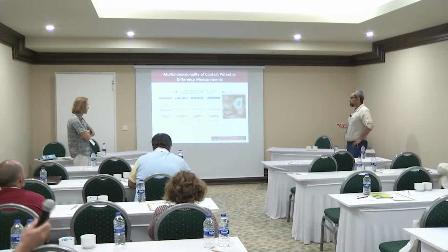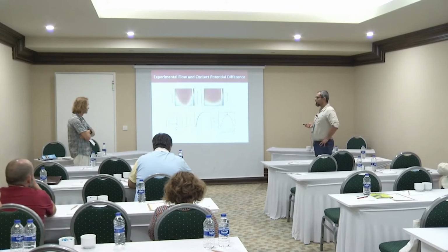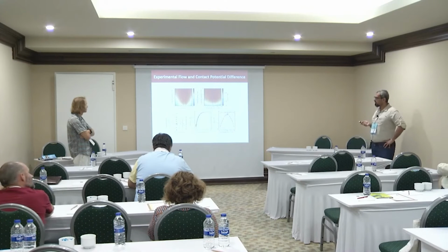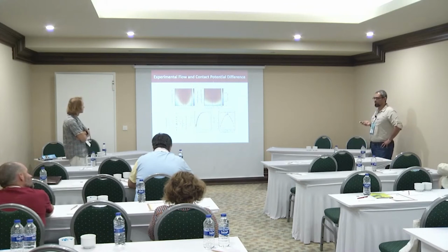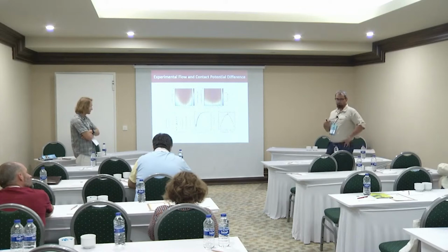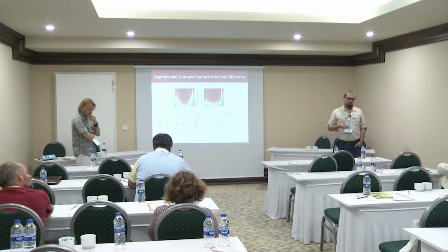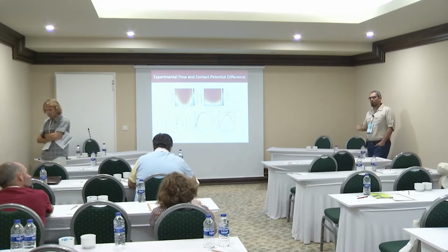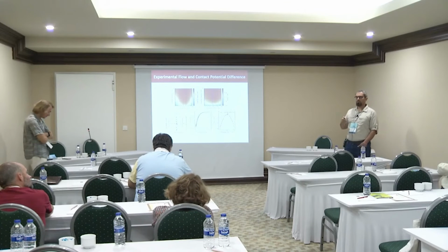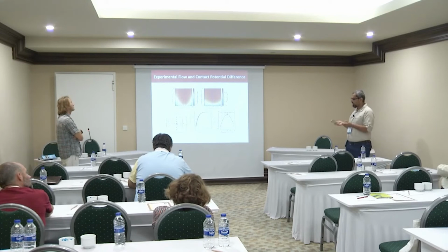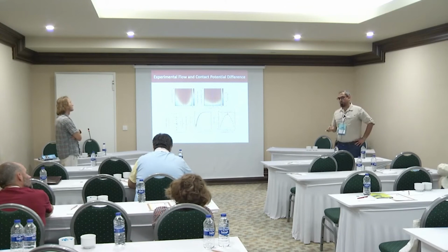Yes, we measured by using different types of cantilevers, and the most important part is that we are measuring the contact potential difference, not the actual Fermi level. So any chemical change in the tip, which may be induced under ambient conditions, may affect the absolute value of our measurement. So we did cyclic measurements. So we measured the properties at different temperatures, and we went back to the original temperature that we measured. Also, we used different types of cantilevers.